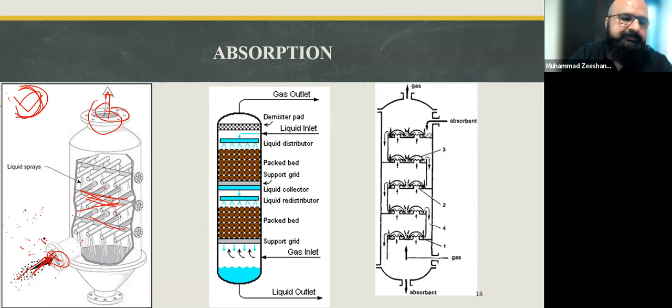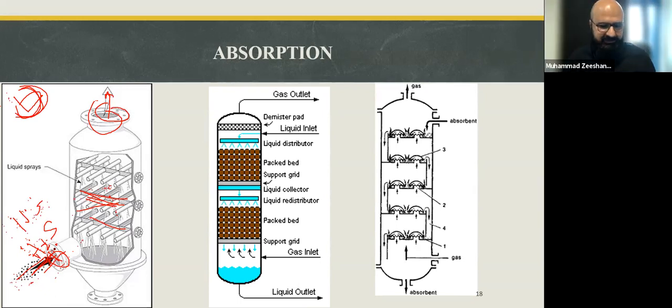as we discussed. And of course, we are supposed to be removing H2S from natural gas. So we pass that dirty natural gas through this column, and this solution absorbs most of the H2S out of it, if not all. Of course, we expect industrial processes not to be 100%, rather even 99.9% is good enough, or even more than enough. So this solution absorbs H2S, and we get cleaner gas at the top,